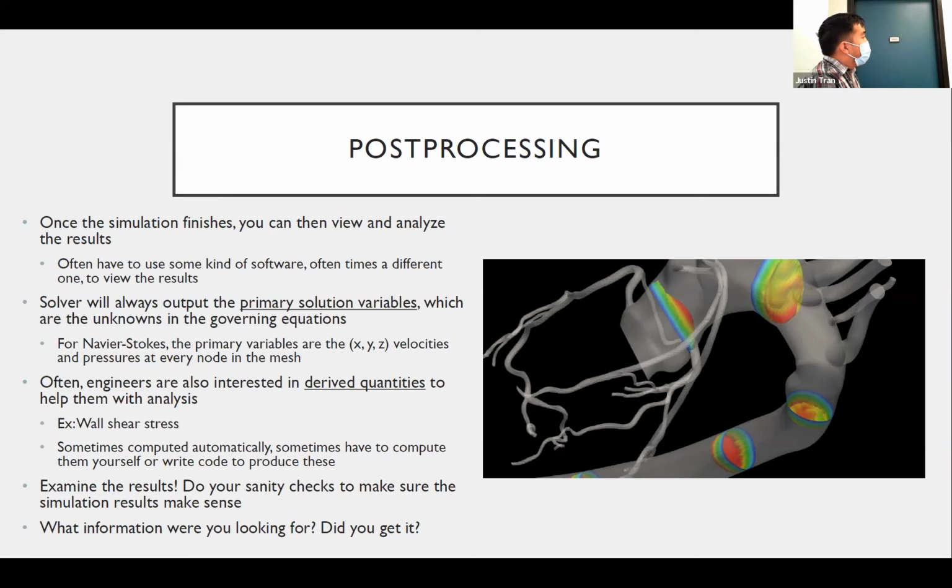And so, this part we're going to spend some time on, and it's hard to explain without really going into some vascular, but this is where you see, so you ran your simulation, so you can start to see what does the velocity field look like? What does the pressure field look like? What does the wall shear stress look like, right? And so this is where you would actually look at it.